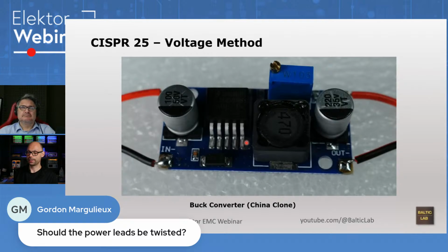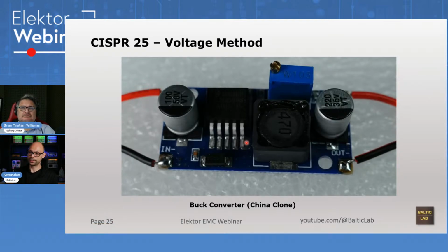The same thing, we haven't shown the case. The device under test is supposed to be 5 centimeters above the reference ground plane. So there's some devices, like, what are those things called that control the motor, ECU, I guess in English. They are often bonded directly to the chassis. If your device is directly bonded to the chassis with its metal casing or whatever, then yes, you will deviate from that in the test setup, and you will also bond it directly to the reference ground plane. So oftentimes the answer is dictated by how you intend your product to be used.